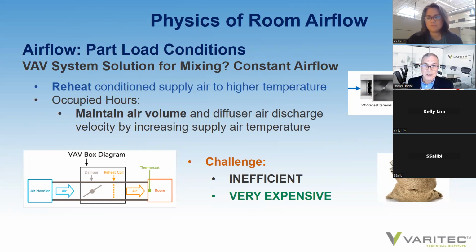In Phoenix, we see 0.3 to 0.35 CFM, maybe 0.4 per square foot of space versus 1 to 1.1 CFM. And it's the reduction of ductwork. And also with the new technology today with air handlers, we can shrink the equipment square footage requirements depending on the system applied.